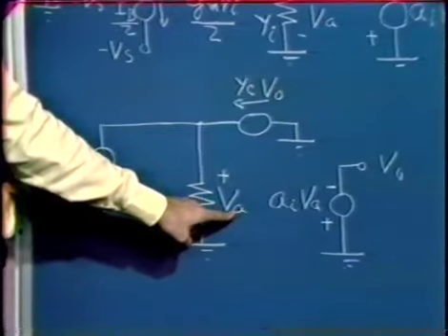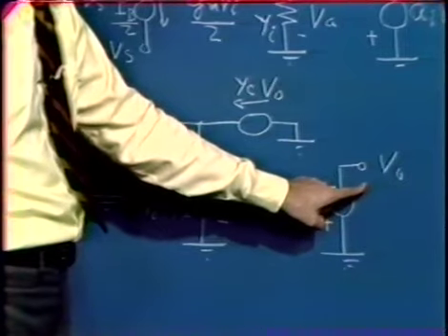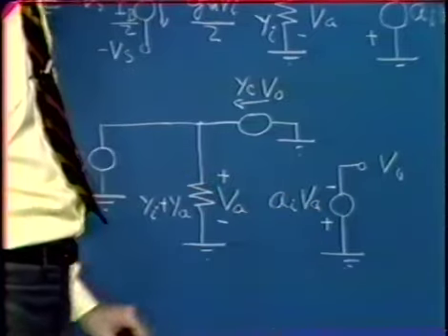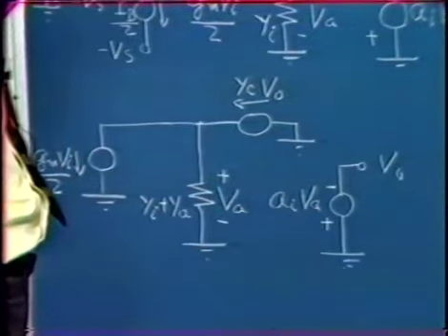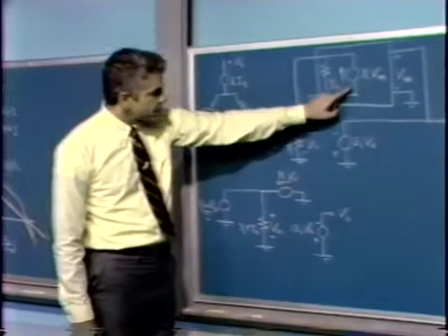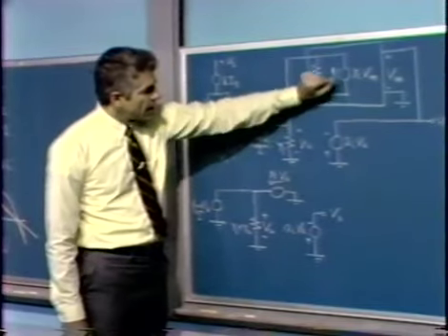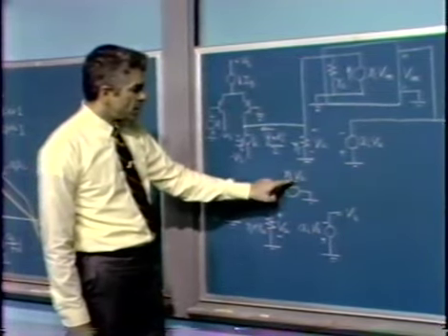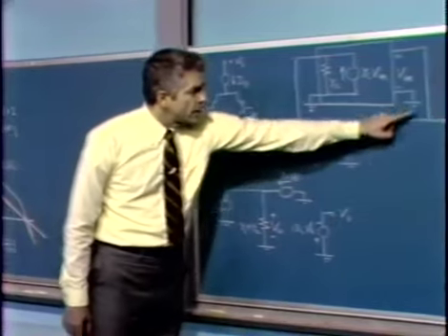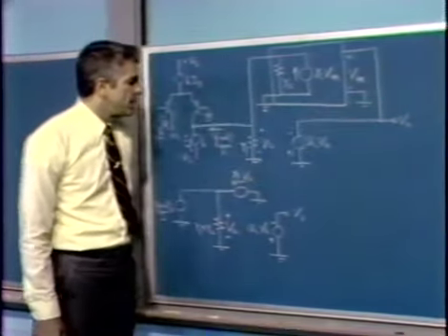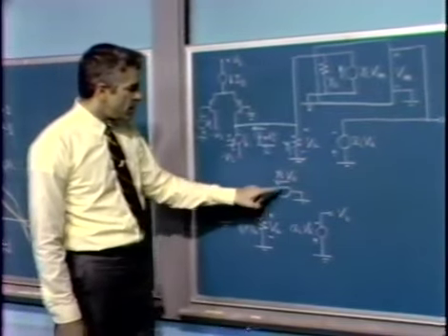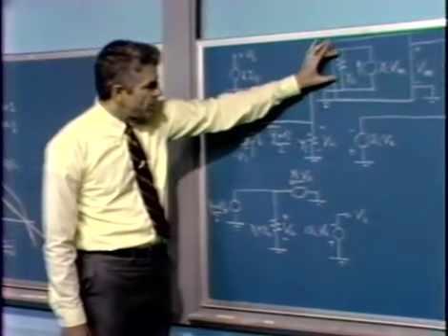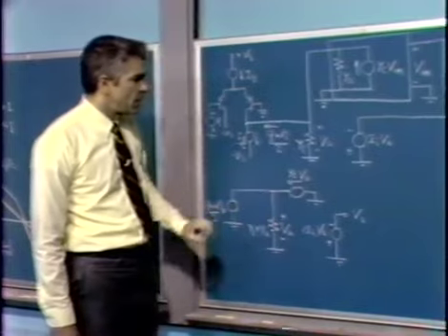The voltage across that admittance is VA, and the output voltage, as it was above, is simply AI times that voltage V sub A. We complete the minor loop, or model the effect of the two-port network as far as its feedback effect, simply as a dependent generator whose magnitude is Y sub C times now VO, recognizing that VO and VM are identical. And so we represent the dependent generator associated with the two-port in this way. We've already taken care of the output admittance of the two-port since we've lumped it into this admittance.